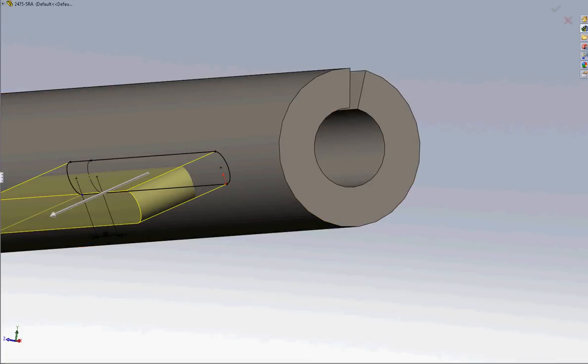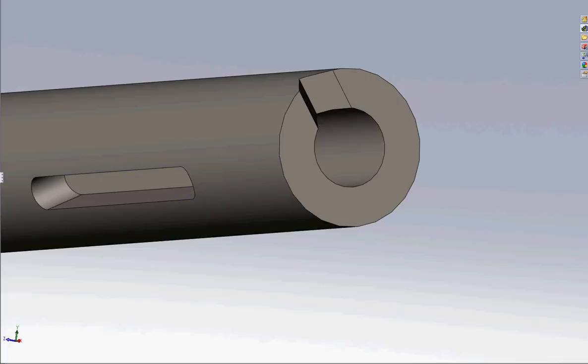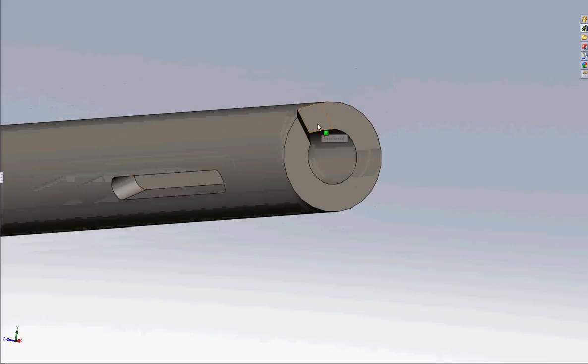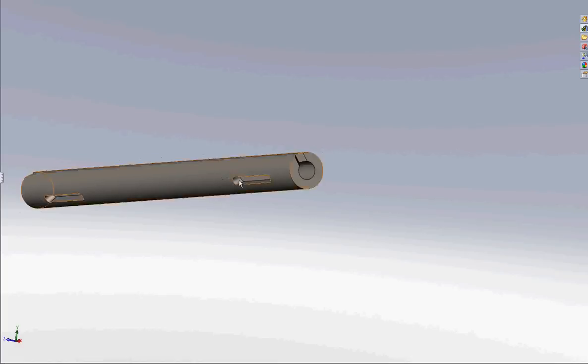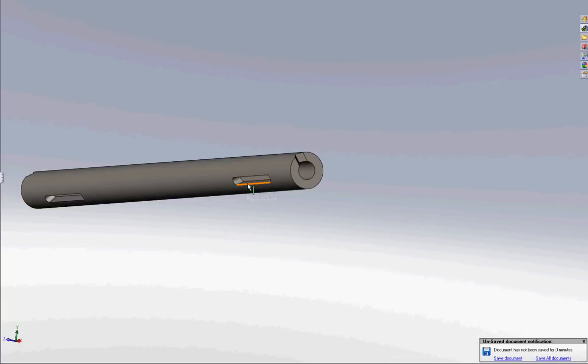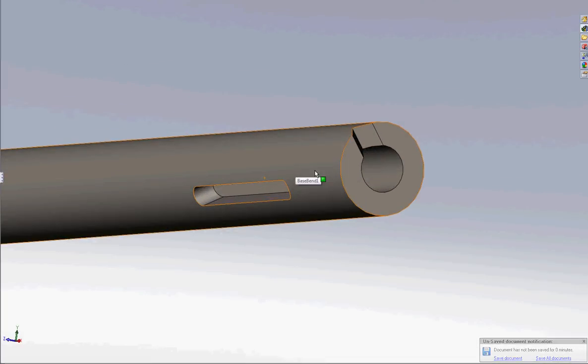No big deal, right? Slot there and triangle out here on the end. So what those are for, this is a function of the product, let's say. This is a fixturing recess. This keys into a pin in the fixture. And what it does is it sets this tube in a certain orientation because these slots have to be clocked a very certain direction for this thing to work.